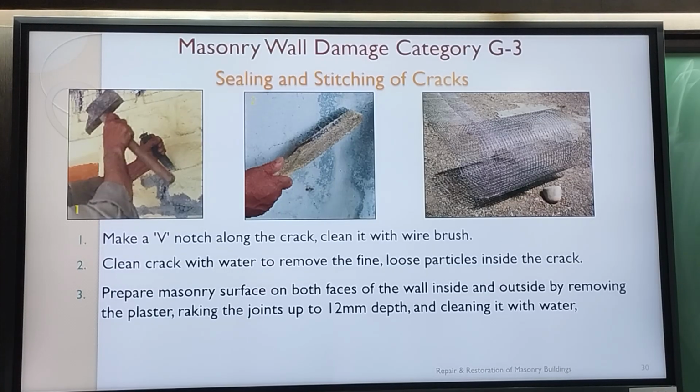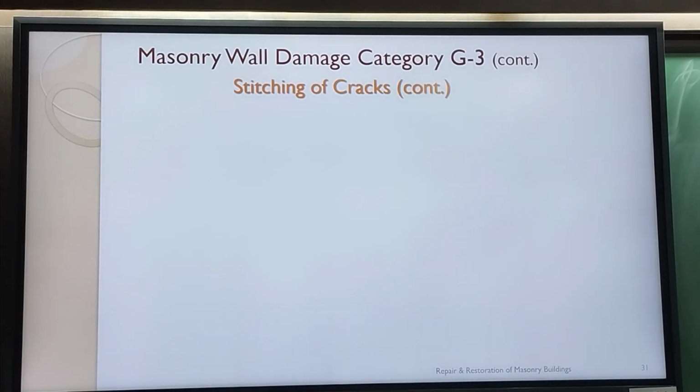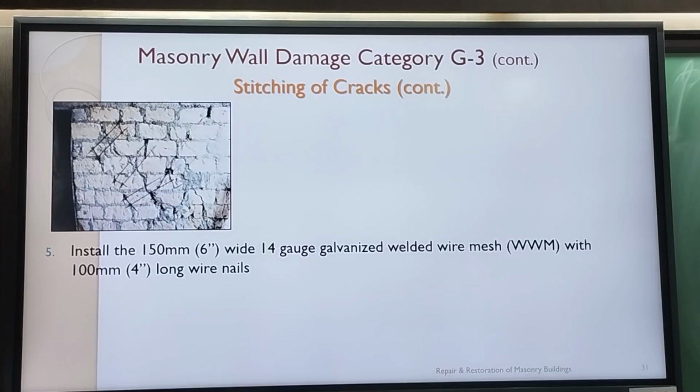You make the V notch and you do the cleaning and all that. But the most important after grouting is putting the splice. The question is what exactly is the splice. It's the stitching of cracks. So there are different situations.